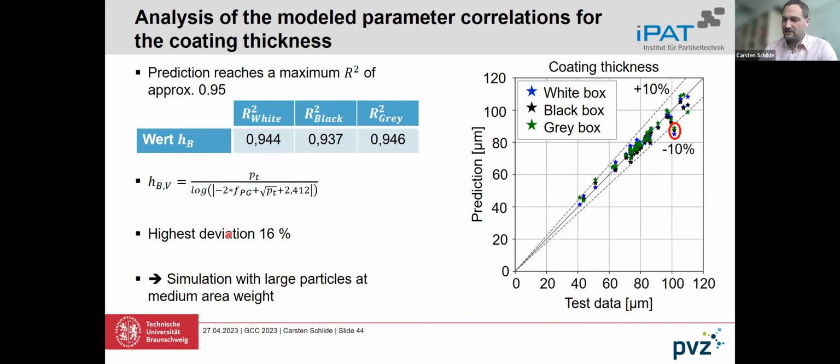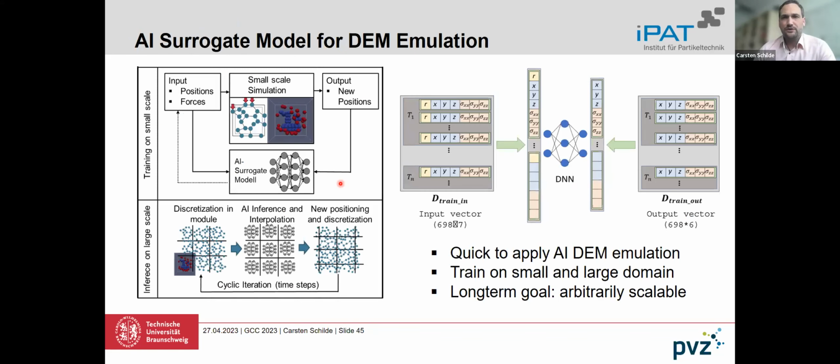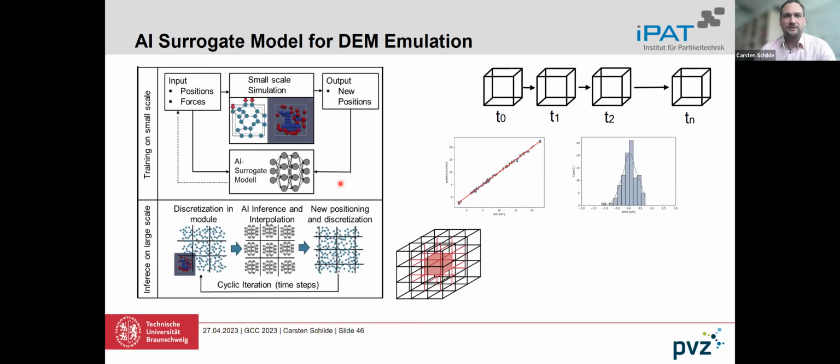So we derive the function of the height of the electrode, of the porosity of the electrode, based on the particle size distribution, based on the areal loading, mass loading, or the initial wet coating thickness. So there are other possibilities. They are more enhanced, for example deriving surrogate models in future, to be faster with the DEM simulations, which I will not explain now.